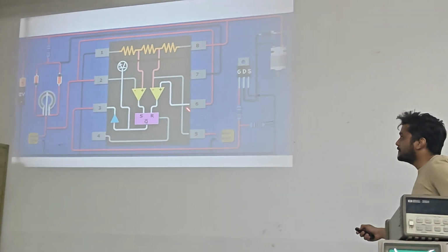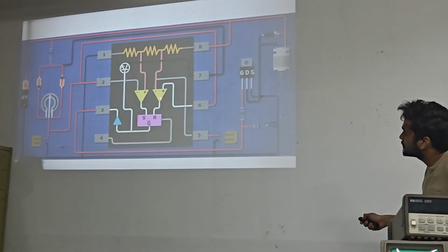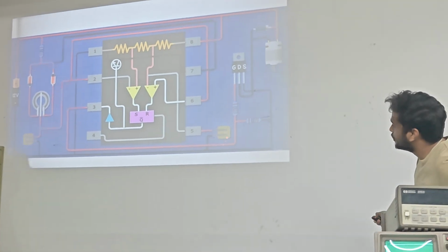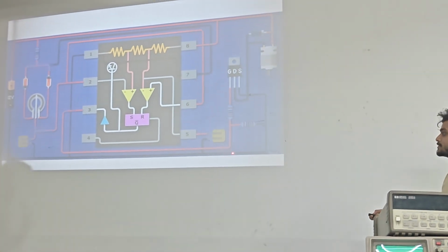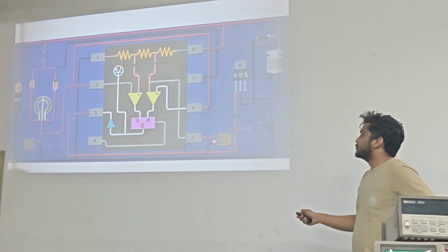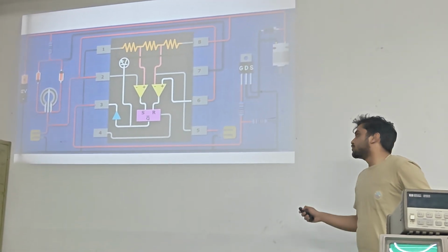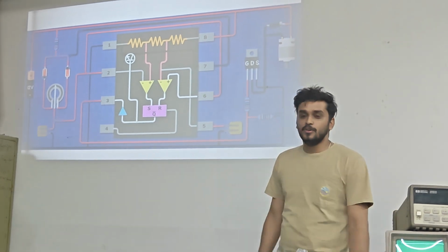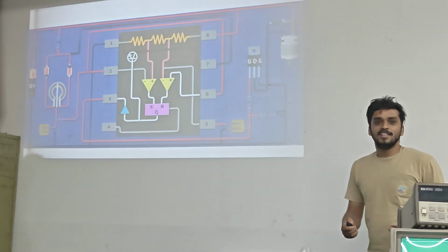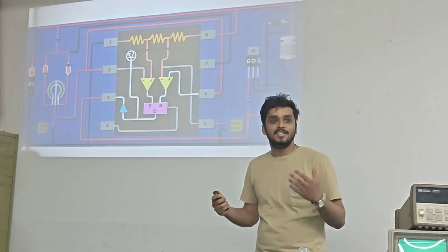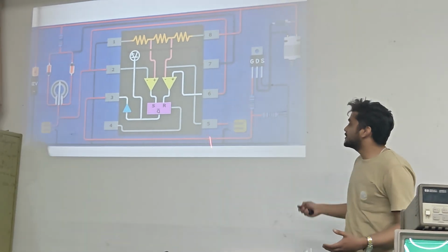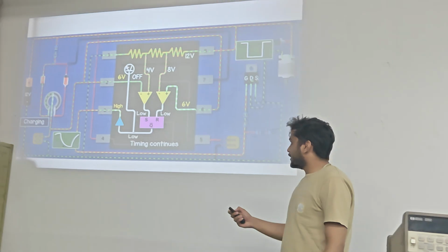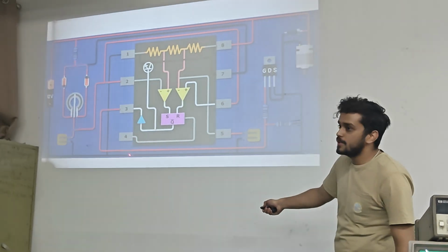This pin number 5 is connected to the minus input, the inverting input terminal, of the second comparator. So we do not need to change that. We have connected this to ground via this capacitor. This capacitor acts as a low impedance path for high frequency noise, right? When the frequency increases, the reactance of the capacitor decreases, so the high frequency noise will go to the ground.